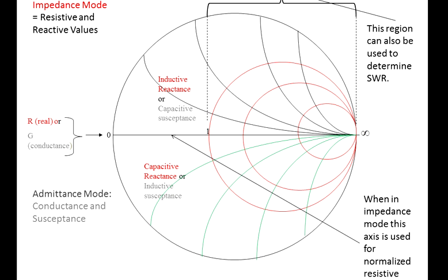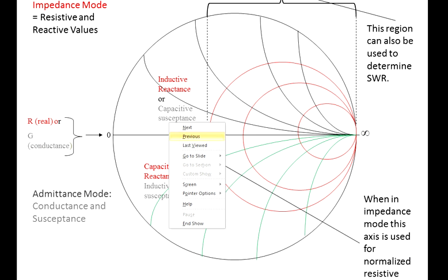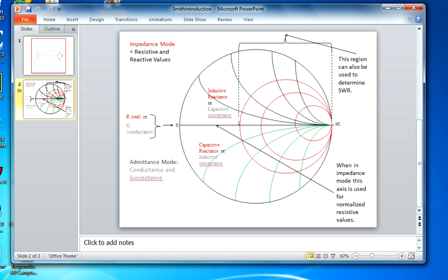So in part 2 we'll show you how to draw an impedance circle, and where the impedance circle draws through that axis down the center, or the middle of the Smith chart, where it intersects that point, that will be your SWR value for your particular scenario. Okay, so we'll go back to the first slide and just do a little bit of a summary.